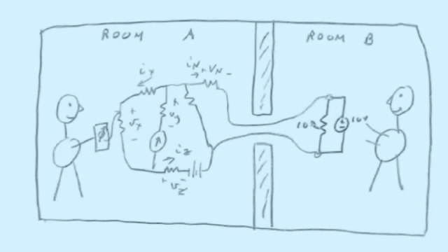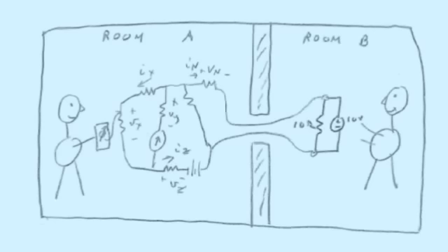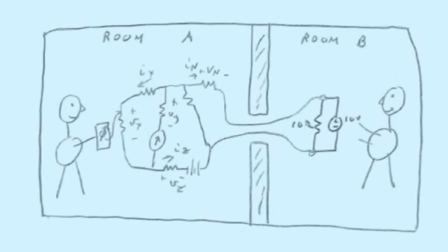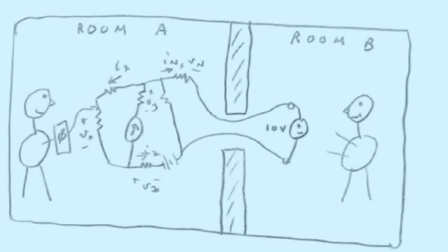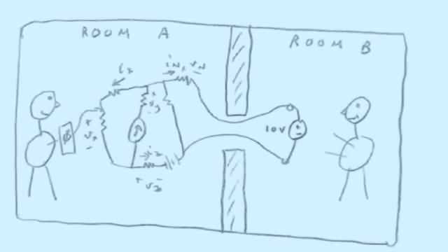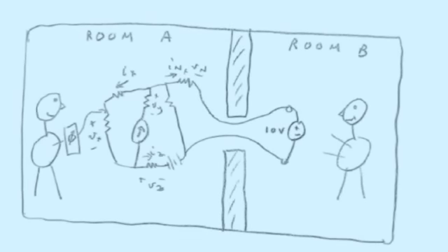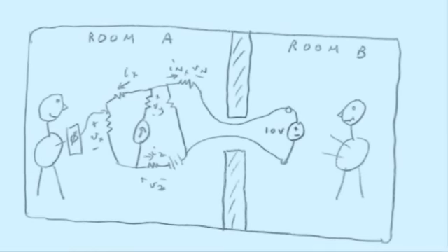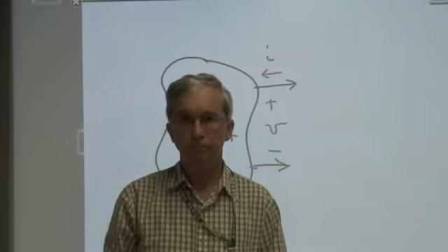In this cartoon of Celine with her circuit in room A, which is connected to Joan's circuit in room B, none of the V and I that Celine's measuring in room A would change at all if Joan removed the parallel resistor. And now Joan's removed that resistor. It's equivalent from Celine's point of view. She represents the, quote, rest of the circuit, end quote, point of view. Of course, from Joan's perspective, it's not the same circuit. Before she had a resistor that was dissipating power. Now she doesn't have that resistor. But from the rest of the circuit's point of view, it's certainly an appropriate simplification.